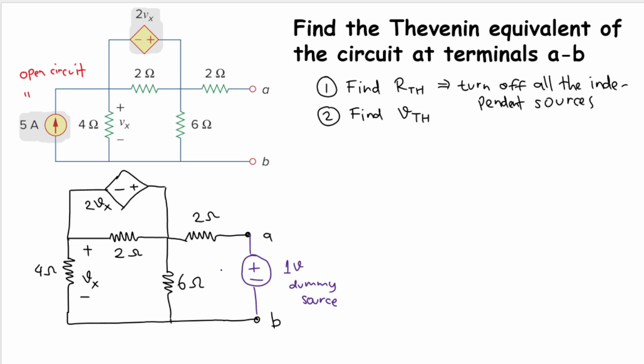And then we know that this will generate the current there. So let's name this I0. So we can find RTH. Let's take a note here. RTH will be 1 volt divided by I0. Good. And I think we can start doing circuit analysis from this circuit here.